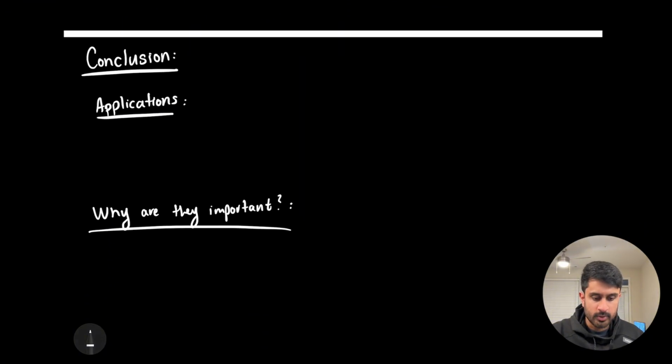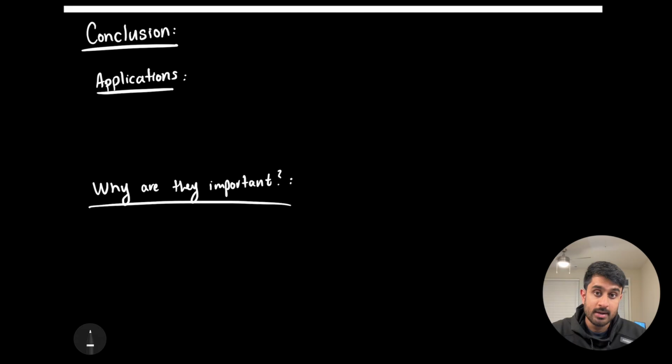So let's wrap up and really understand what we've learned so far. Capacitors are circuit elements specifically used to hold charge within their electric field. If we apply a dielectric within that capacitor, the overall capacitance of the parallel plate capacitor is going to increase significantly via the equation C is equal to epsilon A over D, where A is the area, D is the separation between the plates, and epsilon is the permittivity of the dielectric.